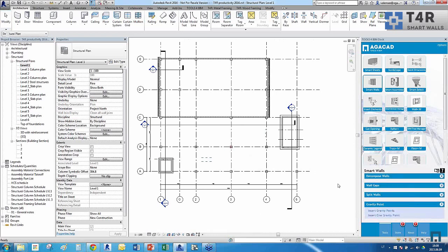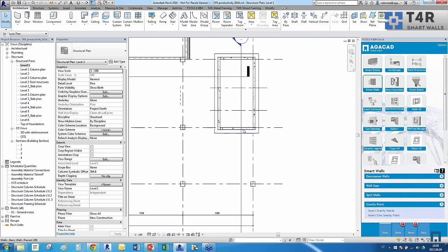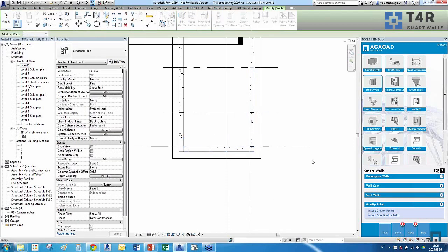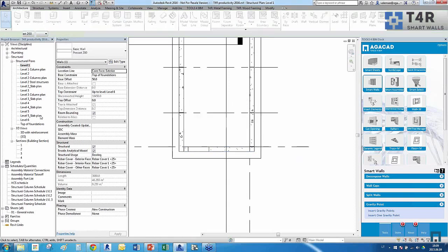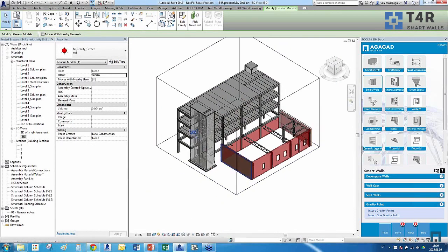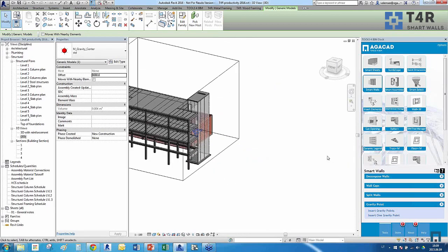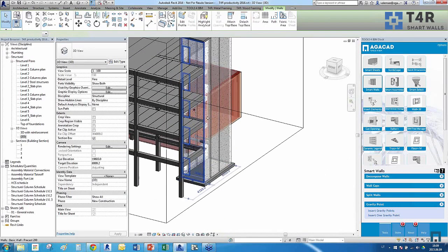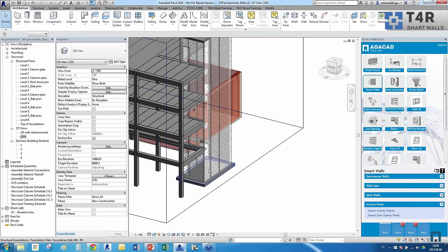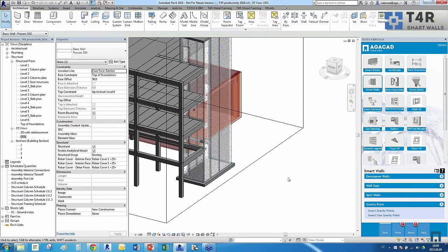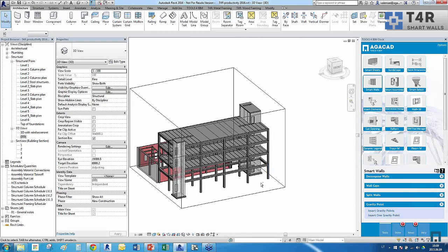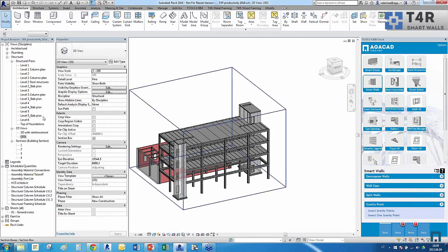Okay. Yeah, you can also insert gravity points into your wall elements. So if you select just a wall element, you click insert gravity point, and you can see the gravity point inserted into your wall panel. I have here the big wall panel. So you can do this for one wall, or you can have a gravity point for a group of walls. You can use it also when you need to define some lifting devices space.